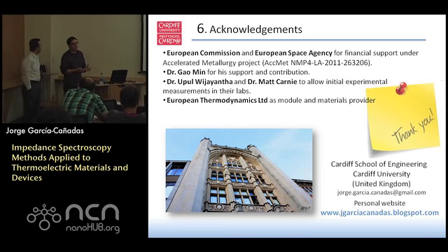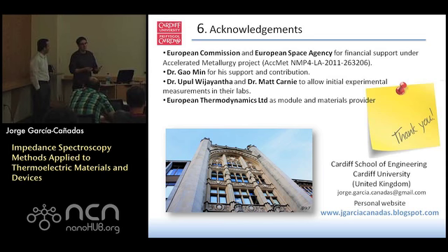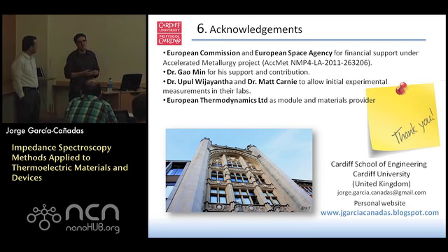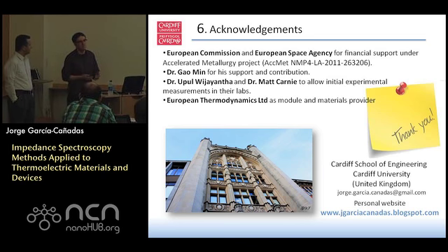When you go to nanostructured materials, it's likely that, for example, non-ideal contacts, non-ohmic contacts, will appear. You can have space charges, and they will appear as a new feature in the impedance spectrum. But I don't know which shape it could have.